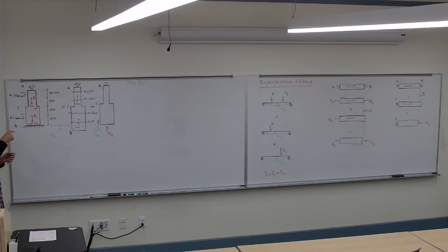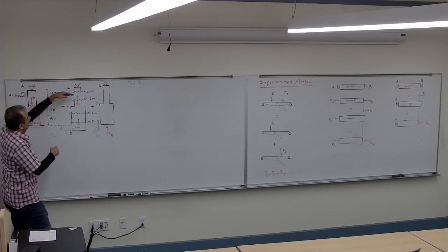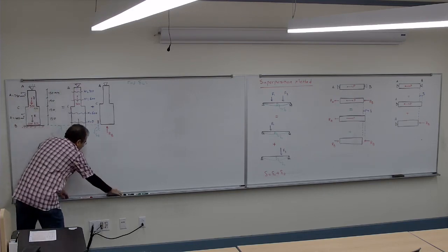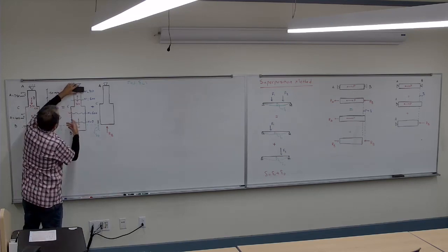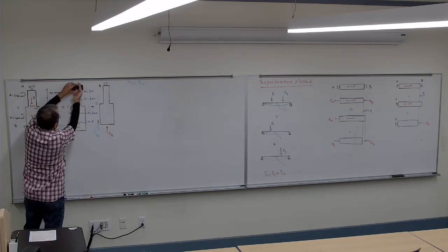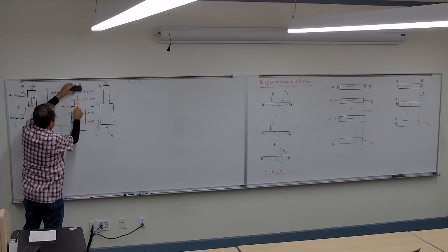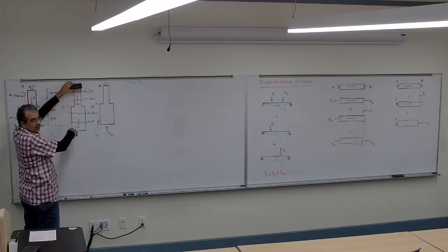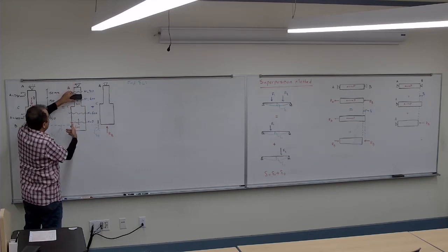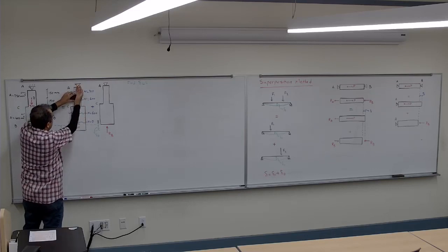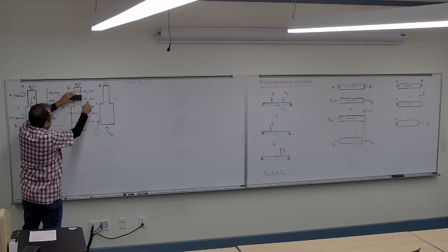Look at that. So forget about the top part. You cut it there and only keep the bottom part. So if I cut it from here and forget about this part, N pulling it up and 300 plus 600 pulling it down. So it's going to be 900. If I cut it here, N pulling it up, 600 pulling it down, so it's going to be 600.